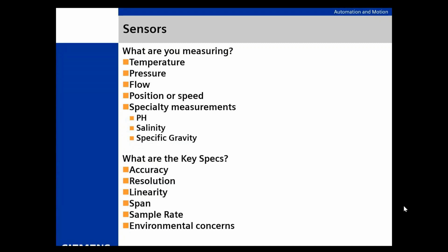But I'm going to ask these questions. What are we really looking at? And I'm going to look at your process. Things like pH and like salinity are horribly nonlinear. It's not like you add a little something and there's this change that follows. That doesn't work. That doesn't happen in the real world most of the time, okay?